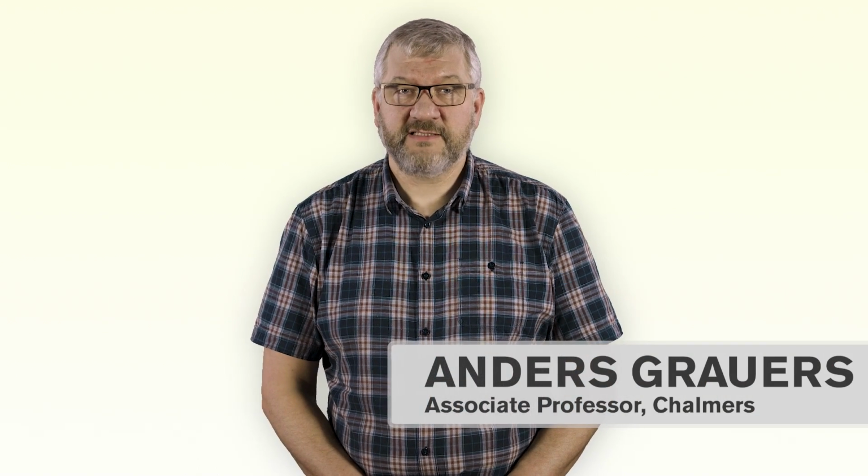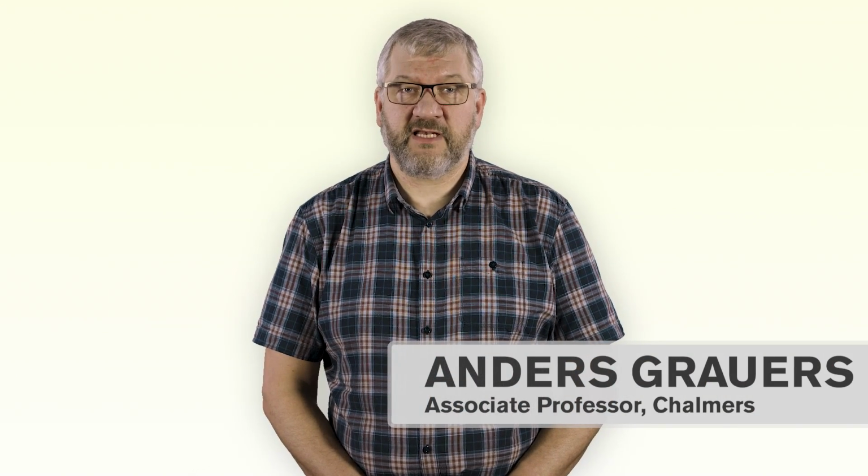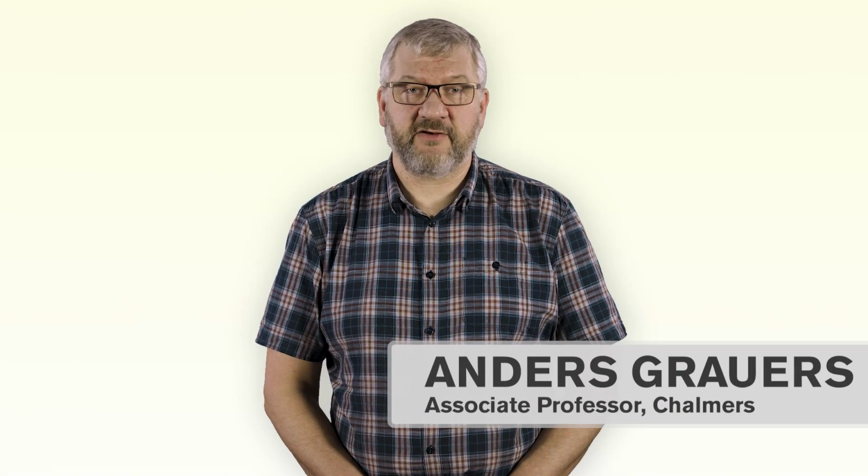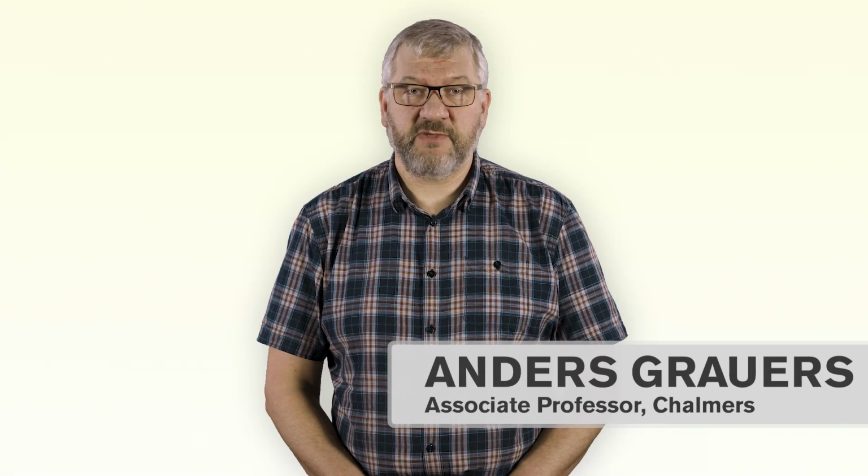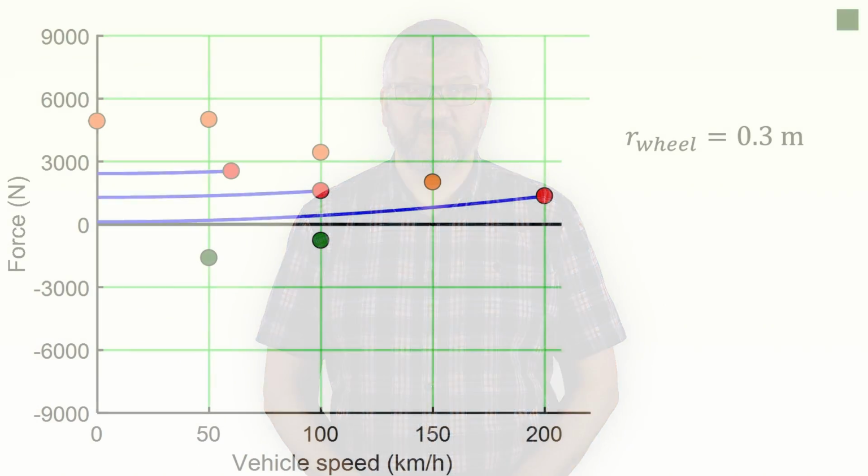Hi again. In this lecture we will study a method for selecting the size of a single gear electric drive system which meets a set of performance requirements. The method starts only from a given maximum speed of the electric machine and assumes we can freely select the maximum torque and maximum power of the electric drive. It also assumes that the drive will be capable of producing constant power in the whole field weakening region.